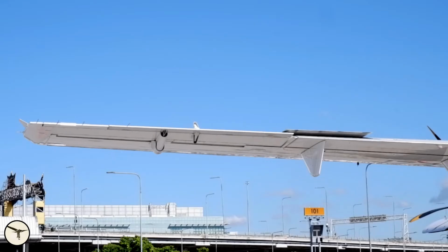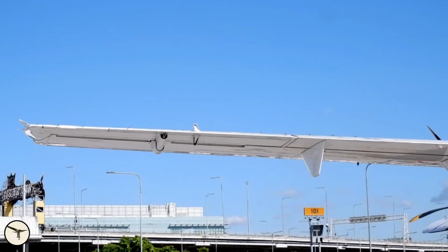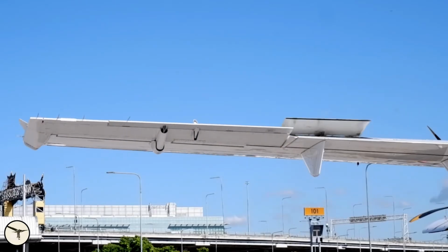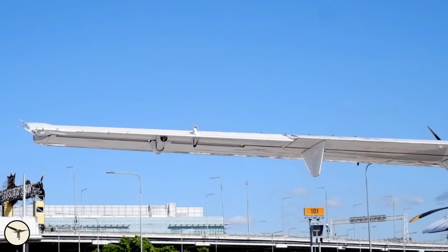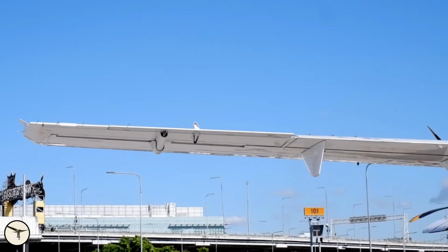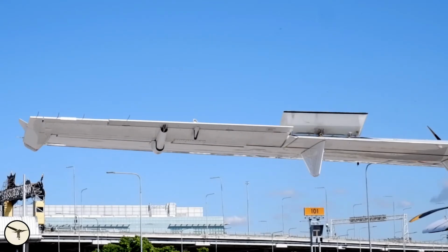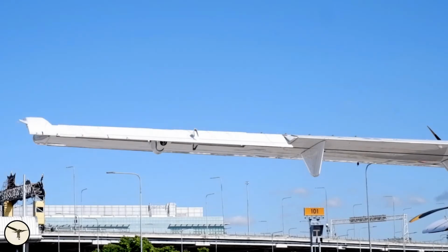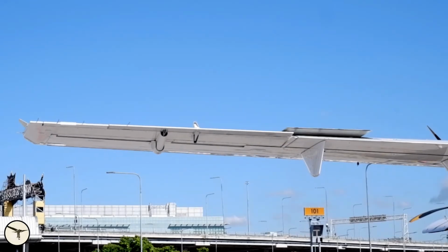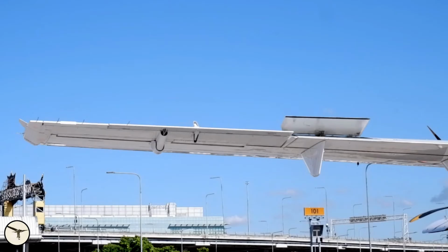And remember, the spoiler creates drag and with it a yawing moment. If you for any reason use the control wheel like you steer a car and you apply left and right aileron, the yawing moment will change, making directional control much harder. Sometimes I see pilots who are clever to hold the ailerons into the wind at takeoff, but they forget to do the same at landing.